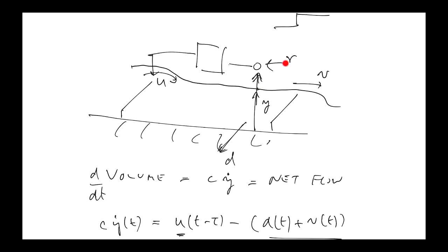We're trying to control it to some set point level that's determined on the basis of demand. Okay, so we look at the difference between the water level and the reference. That generates an error signal that's processed by a controller that adjusts the upstream flow.